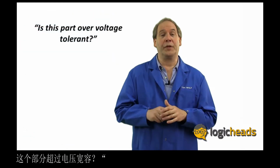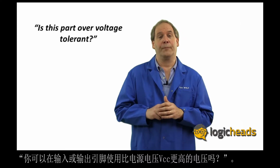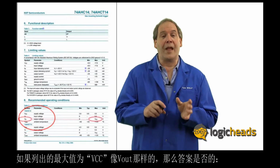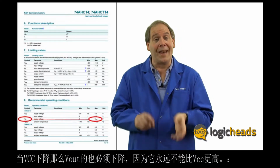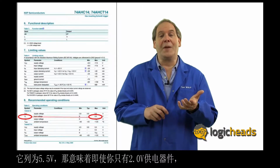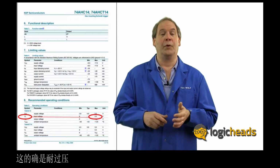Is this part overvoltage tolerant? Overvoltage tolerant means, can you put more voltage on the input or output pin than the supply voltage of VCC? The answer is right here in the recommended value chart. If the value listed is VCC, like for Vout, then the answer is no, because as VCC drops, the Vout must also drop because it can never be higher than VCC. But notice the max value for the Vin. It's listed as 5.5 volts, which means even if you power the device with only 2 volts, you can still let the input see 5.5 volts. It is indeed overvoltage tolerant.